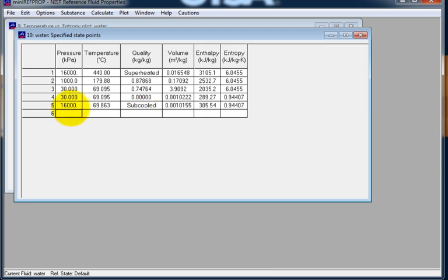All right. What about state 6? Didn't they say it was that high pressure? But what was the temperature? It was the saturation temperature. Well, I look it up and type it in, or I just realize, hey, I got it right there. Isn't it the temperature at state 2? So I just go up, copy it from state 2, bring it down and paste, and then there you go. Almost too easy. That's pretty hard to do in your tables. State 6 would be hard.